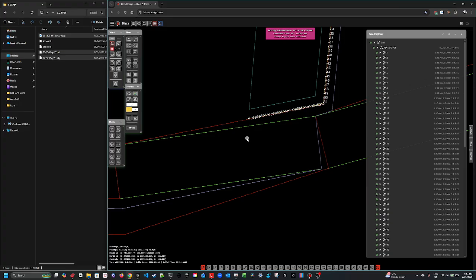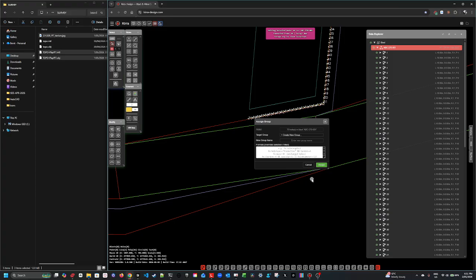And if you want to, you can group these with a new feature, which is a grouping, and we can assign a group to those holes. And so we can either select them and assign a group, or we can use a formula. If we wanted to use a formula, we would type something like fx colon, and then subdrill length, capital L there, equals 0.